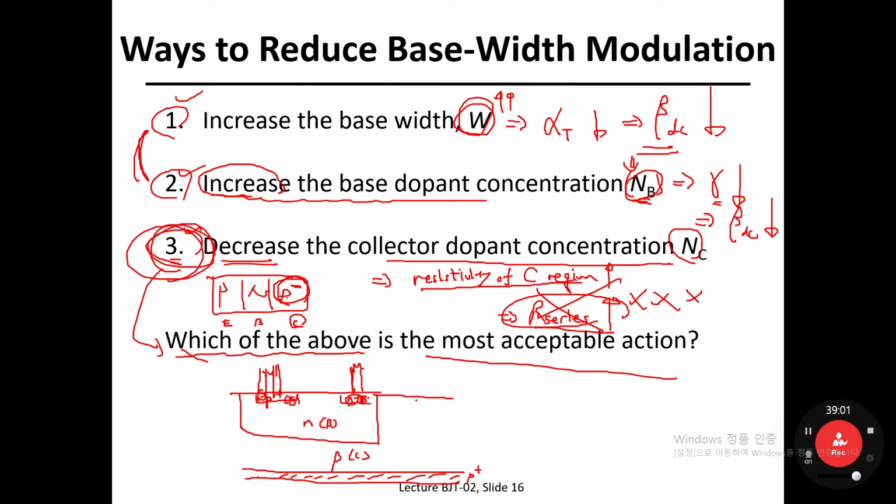Why is N plus necessary to deliver electrical signal to this N-type base region? Yeah, think about the MS Schottky diode, the practical option for an MS diode to achieve ohmic contact between metal and semiconductor. If the semiconductor is super highly doped, then the electron can move in both directions. So we're going to implement the ohmic contact between MS. That is the main reason why we are going to use a heavily doped N plus regime near the metal contact. Anyhow, emitter, base, collector.